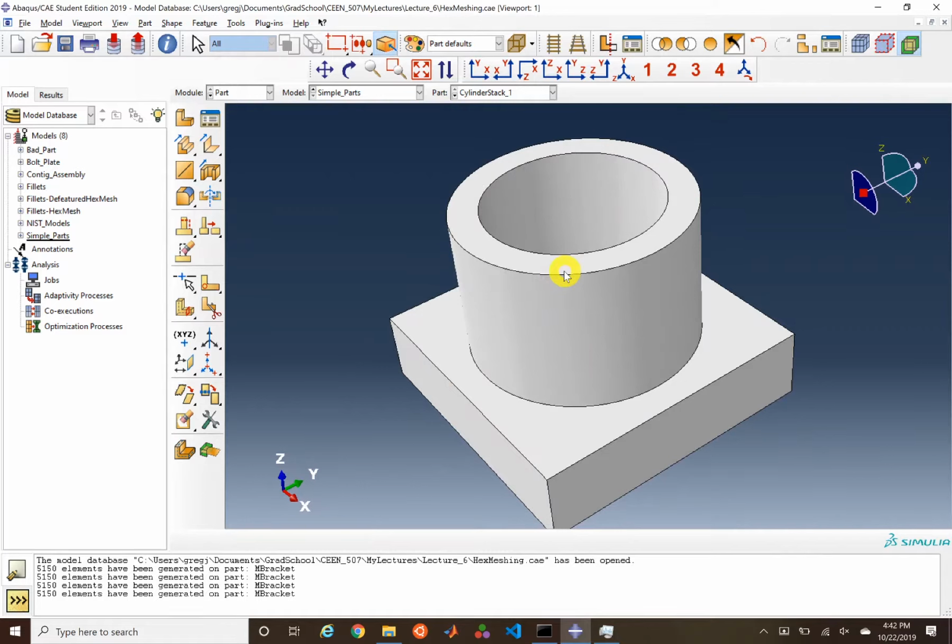Unfortunately, Abaqus can't visualize like you can. It needs to be provided with some simplified geometry regions that it knows how to construct a mesh on, that its algorithms are designed for. And so mesh generation is really all a game about taking the geometry and constructing a very coarse hex mesh on the geometry side that then Abaqus knows how to refine. It's really kind of what this is.